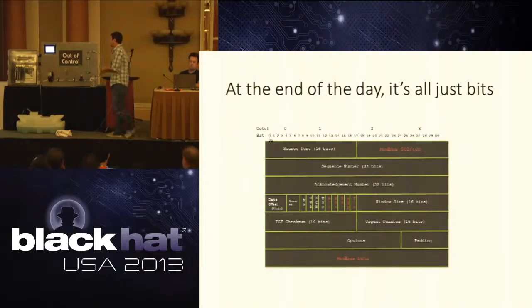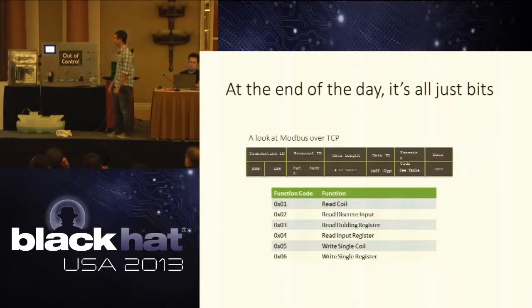So at the end of the day, what we want to do is construct a Modbus datagram. And when we construct that Modbus datagram, we want to send a signal out to this PLC to drive outputs, regardless of whether or not there's safety logic involved. I'm sure everybody's seen this before. This is a regular old TCP datagram, but we're going to do Modbus, which is TCP port 502, and we're going to add our own Modbus data in here to drive this process.